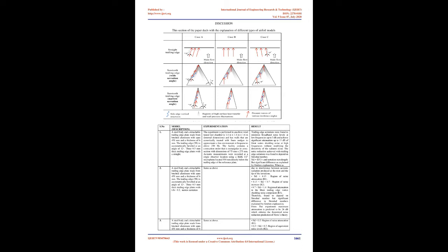Microphones are embedded in the flat plate under a pinhole of diameter 0.4 mm. All pinholes are created by drilling the flat plate using an accurate drill machine. Due to its thickness, the pinhole can be created vertically and microphones positioned under the pinholes at the TE near the TE. The microphones have been installed inside the flat plate parallel to the surface.